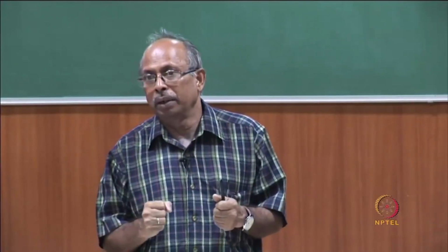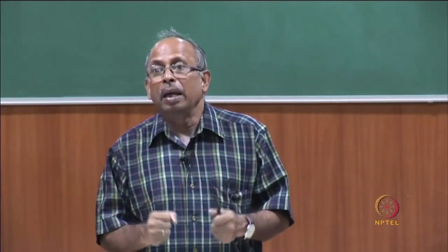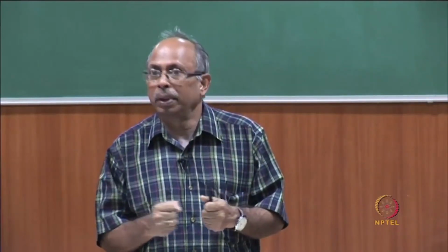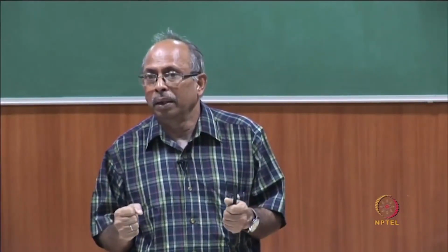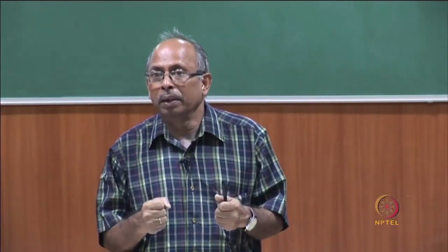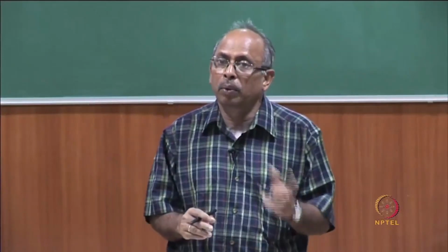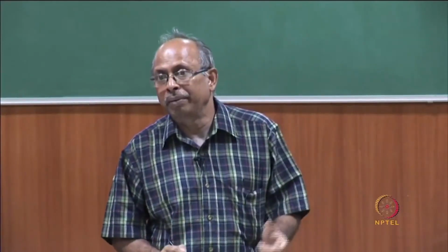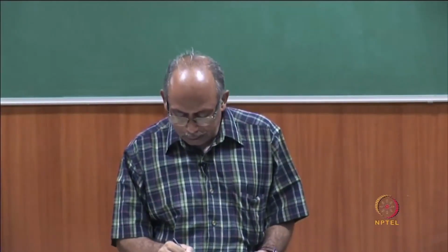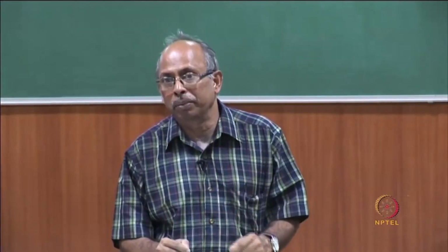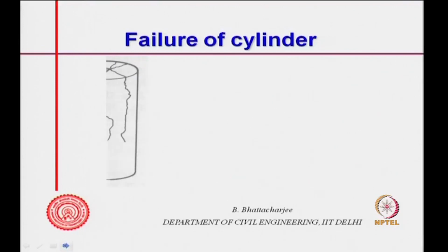concrete is important, right. In weak concrete, restraining effect will be more, because it wants to expand, but if you are not allowing it, this effect will be more, and you can see how the capping material has actually affected it. So, depending upon the strength of the concrete, relative motion of the concrete with respect to the capping material would differ, and that is what it is.